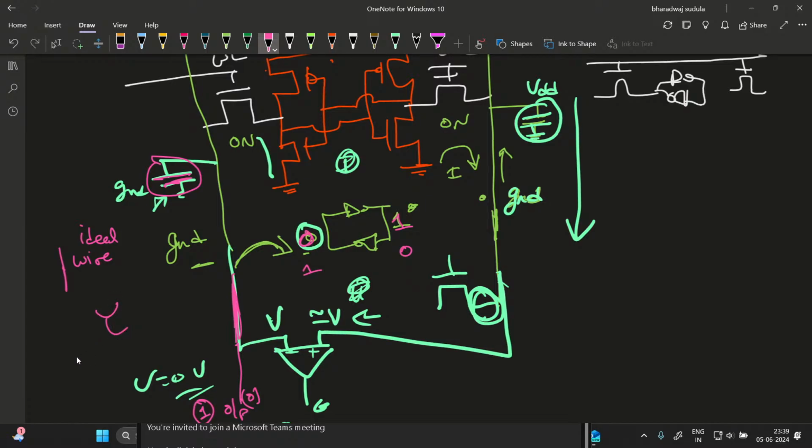So in order to charge up this bit line capacitor, it takes some finite amount of time. But in memories, we do not have that much time to read each cell value. It should be very fast, with some Mbps of speed. So I will be turning on this SRAM cell for a very small fraction of a second, some nanoseconds.